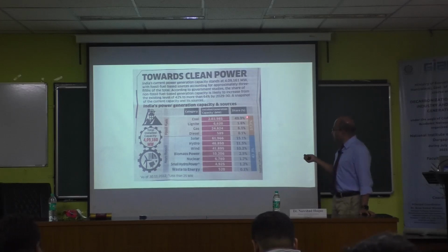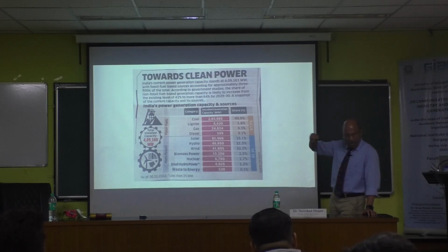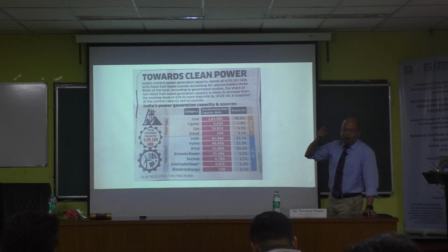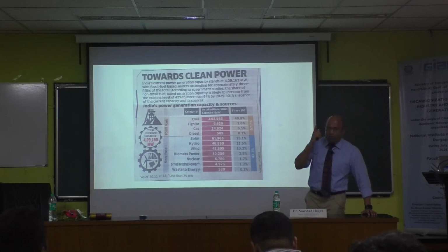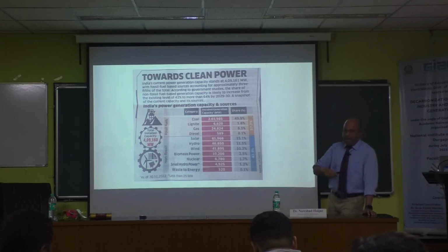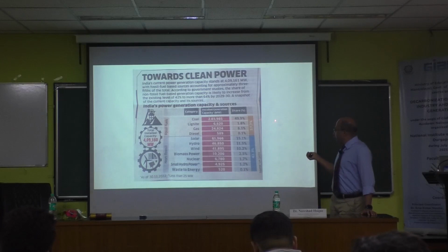So that one, I say that's coal. You multiply by that, and that many megawatt hours of electricity will be generated, hopefully. And 1 megawatt hour of electricity generated means about 1 ton of CO2 for a coal-fired power station, plus or minus, depending on the type of coal. So generally say 1 kilogram per kilowatt hour unit of electricity from a coal-fired power plant. Approximately 0.9 to 1. Yes, 1 to 1, or 0.9. Yeah, similar.